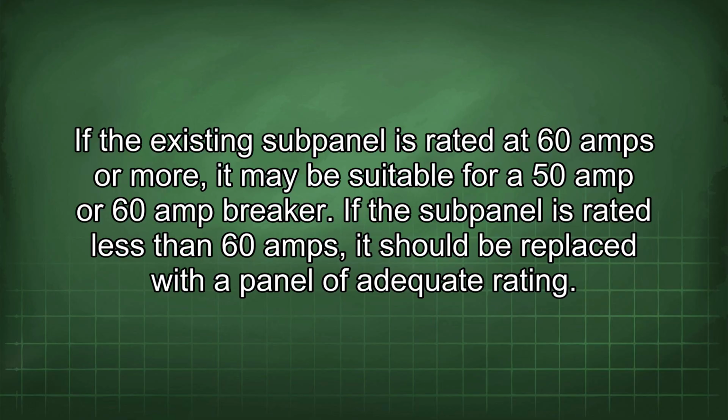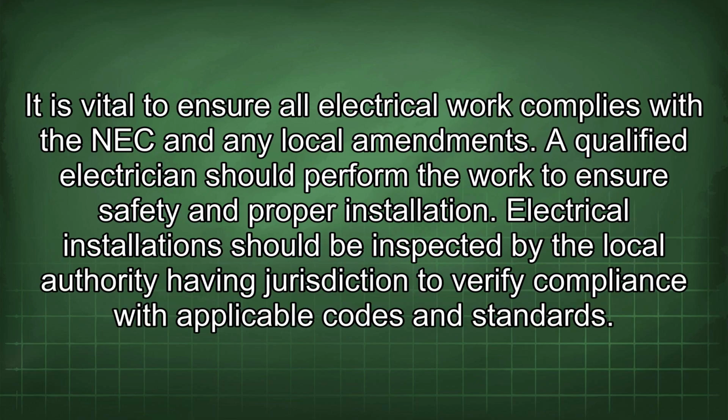If the subpanel is rated less than 60 amps, it should be replaced with a panel of adequate rating. It is vital to ensure all electrical work complies with the NEC and any local amendments. A qualified electrician should perform the work to ensure safety and proper installation. Electrical installation should be inspected by the local authority having jurisdiction to verify compliance with applicable codes and standards.